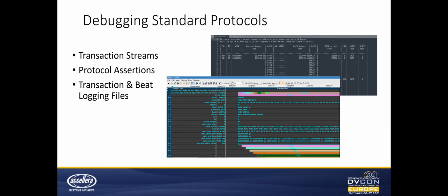And because this high-level verification approach allows us to leverage the same verification tools and techniques that we'd be using at the RTL level, we can take full advantage of what standard off-the-shelf verification IP has to offer by way of debug. In this scenario, since our accelerator design uses AXI4 interfaces for both configuration and data, we used readily available verification IP from Questa to drive and monitor those buses.